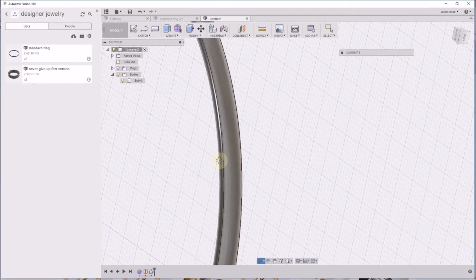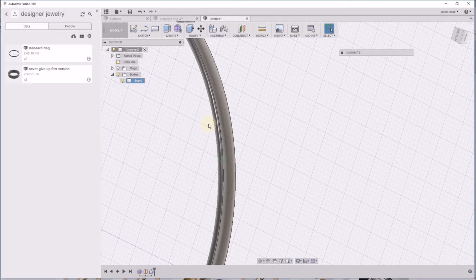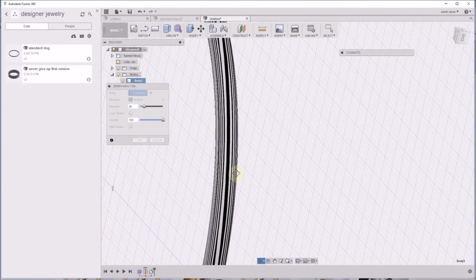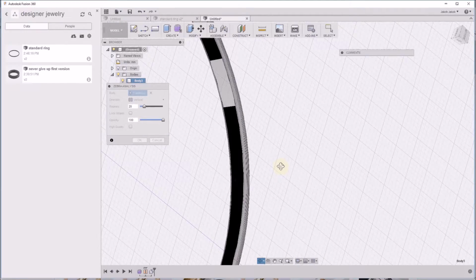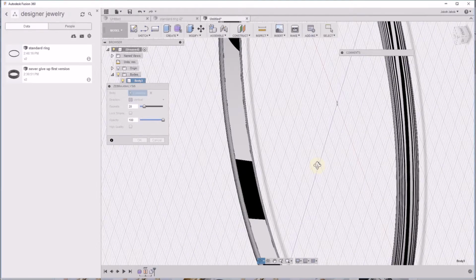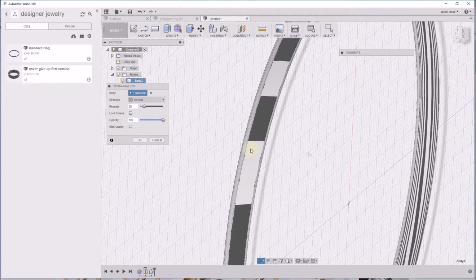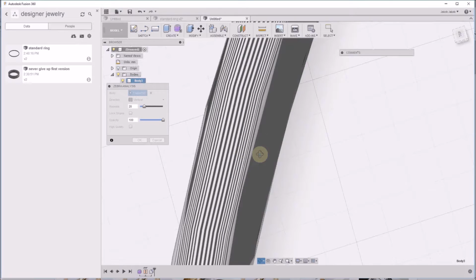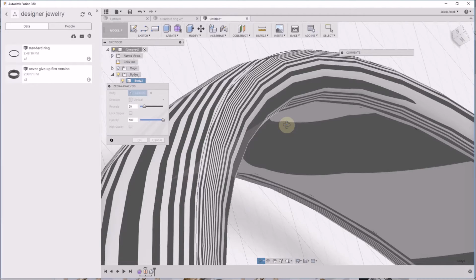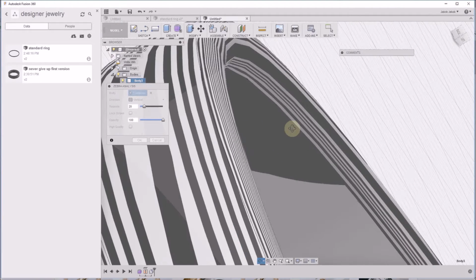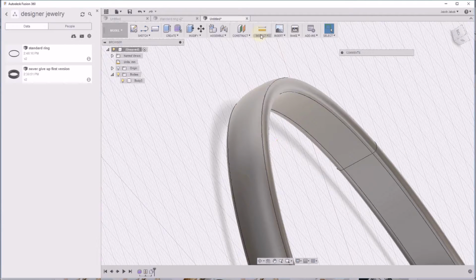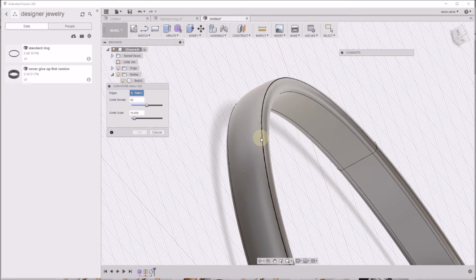And if you should check if the radius is good, you can always go to inspect zebra brush, and you can see that if they are good, it should be not so much contrast. Like you see, this flat compared to other is completely the opposite. Here it is, it's not so bad. Yeah, I think that's nice. Yeah, you can always use the curvature combo also.